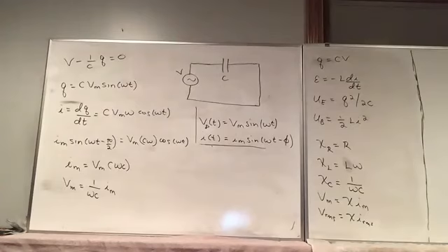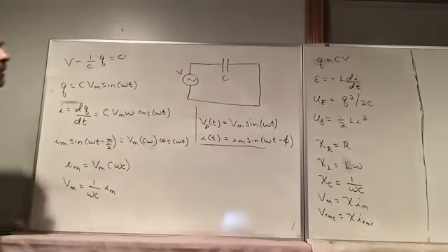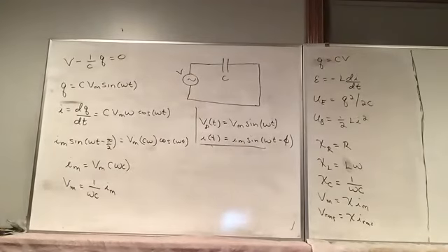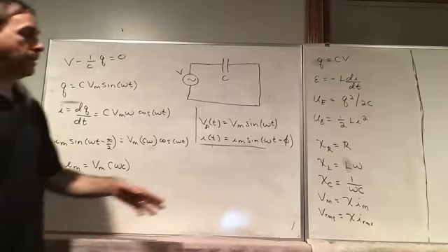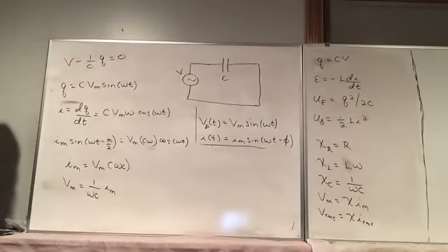Okay, so that's basically Ohm's law for alternating currents, and very useful, even by themselves, if you just have simple circuits like this. You have to understand that these equations only apply to the maximum values or the RMS values, but they don't take the phase difference into account.